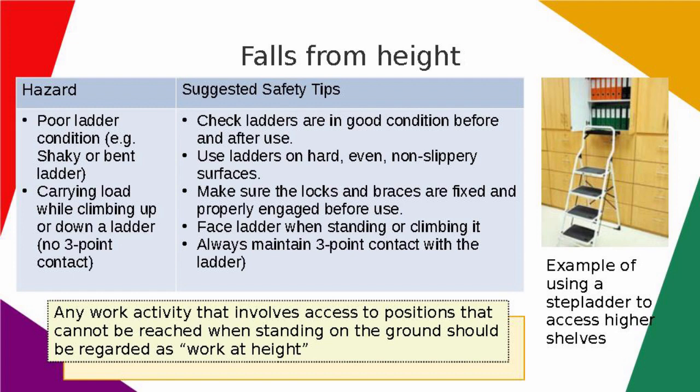Suggested safety tips. Check ladders are in good condition before and after use. Use ladders on hard, even, non-slippery surfaces. Make sure the locks and braces are fixed and properly engaged before use. Face ladder when standing or climbing it. Always maintain three-point contact with the ladder.